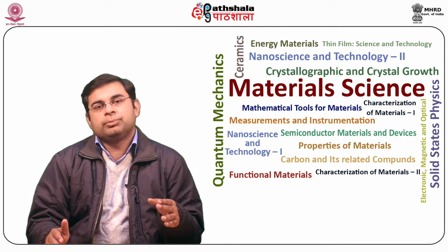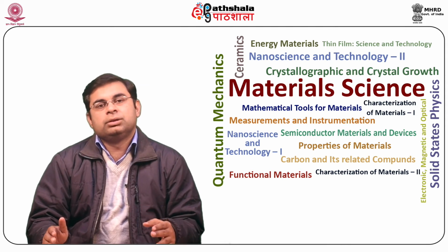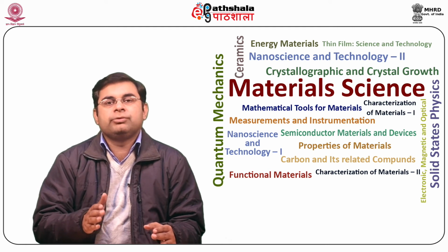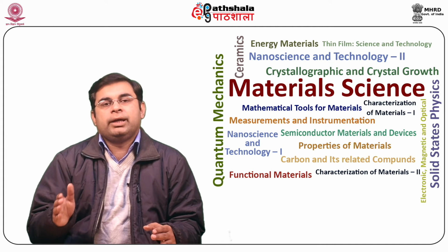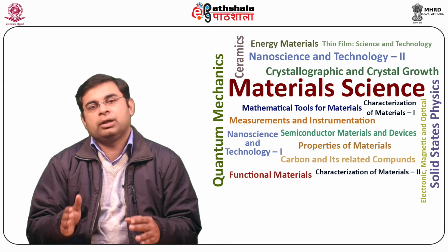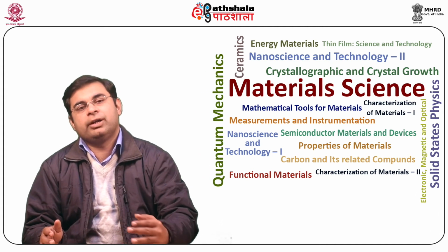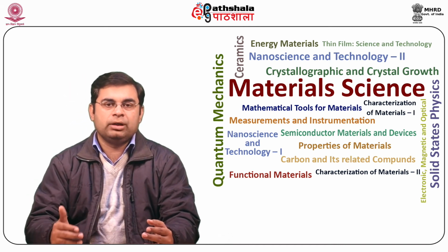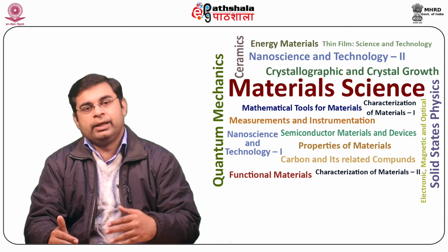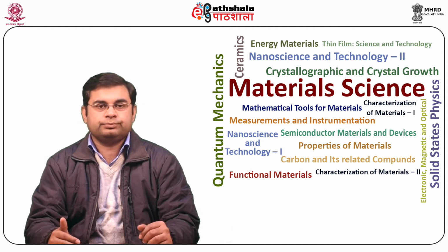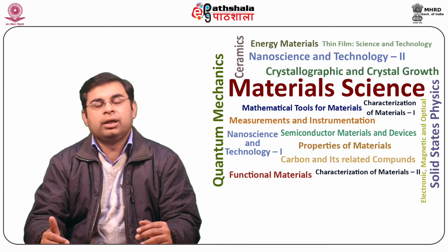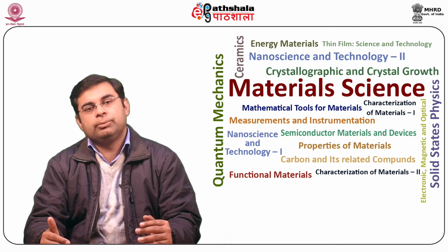Here m is the molecular weight of the semiconductor, Z is the dissolution valency, that is the number of charge carriers spent in dissolving a single semiconductor atom, F is the Faraday's constant, rho is the semiconductor density, and A is the contact area. The measurement depth of the carrier density is given by W is equal to Wd plus Wr.